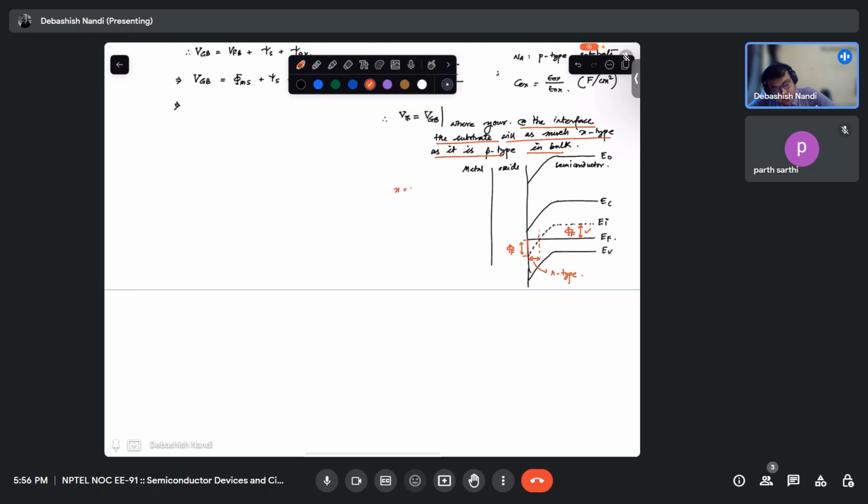You remember, n is ni times exponential EF minus EI over KT. As this distance will be more, my material will be more n-type, and this distance I am calling q phi f.